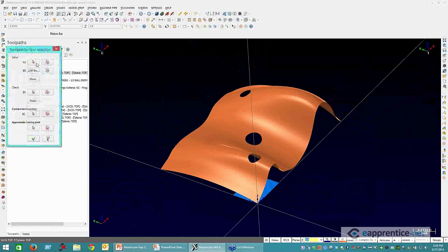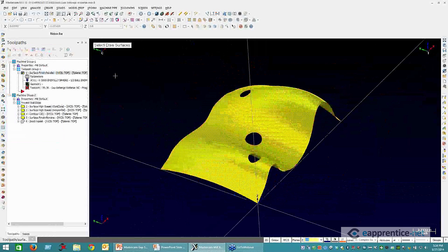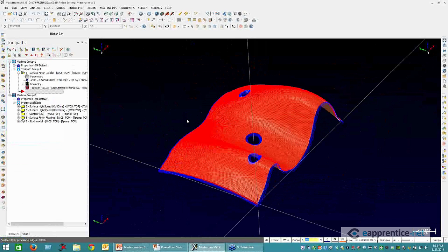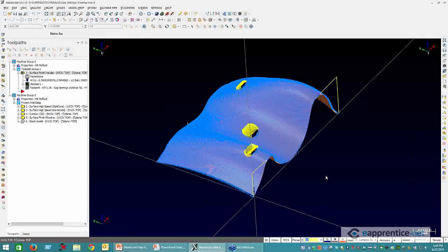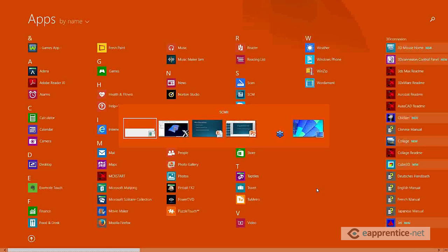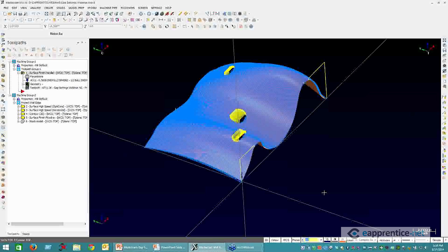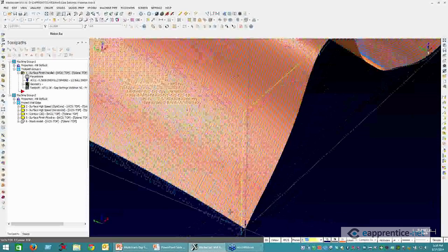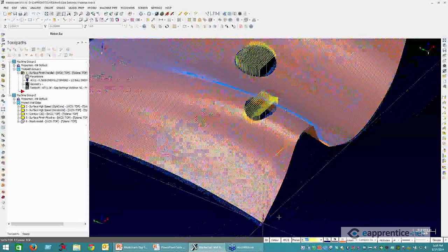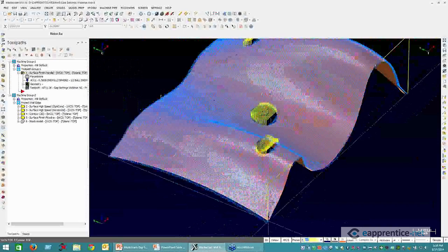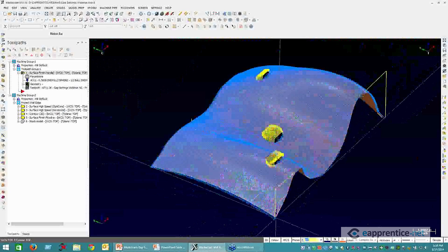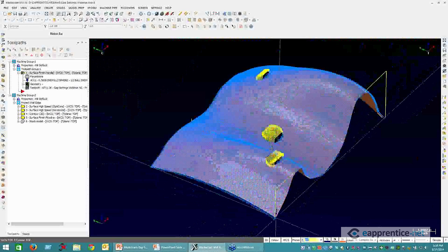So I'll take this toolpath and apply it to this surface instead, and I'll regen it. So now we can see that we've got some areas where we're driving and we're still basically just tangent to that surface. We've got a couple areas where we've got some broken motion. We've got one here. And then we have the motion on these holes as well.